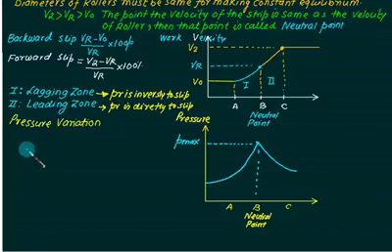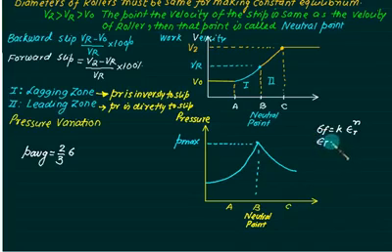Now do not remember the equation that I am giving you, P average. P average is given by 2 by 3 sigma f. Yesterday we got the flow equation. The flow curve is given by K into epsilon to the power N. What is N? Strain hardening. What is epsilon? True strain. In manufacturing we use true strain, so every time we will not write epsilon T. Epsilon T we defined as ln of initial thickness divided by final thickness. K is called the strength coefficient and N is called the strain hardening coefficient.